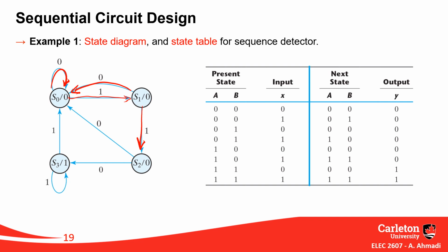When you find the second one, if you get a 0, you go back to state 0. If you have 1, this is a typo from the book, it should be 1. If you get another one, you go to S3, I'm sorry, you go to S3. At S3, you have found at least 3 ones after each other.